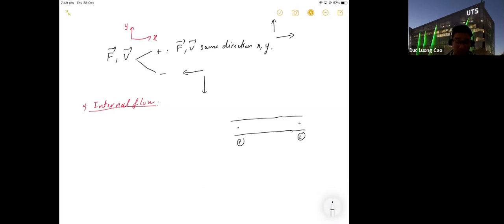For example, here, remember we want to find delta P, and to get the equation in the lecture note, you write the energy equation between point 1 and point 2: P1 over rho g plus V1 square over 2g, that's 1, will be equal to P2 over rho g plus V2 square over 2g, that's 2, plus the energy loss. Between 1 and 2, you don't have a fitting, no elbow or something like that, so any loss in this case is only friction loss, or Sf.